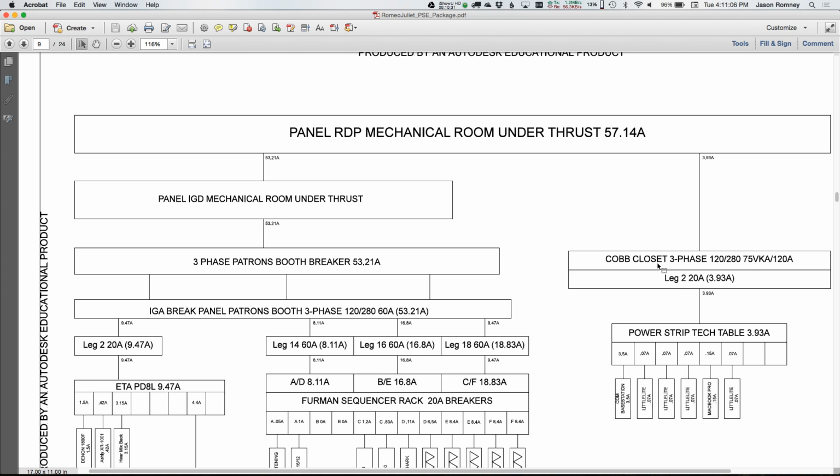If you're finding that you're pulling too much current off something, you need to find another circuit somewhere along the way. This is nowhere near as complicated for us as it is for people who do lighting and MoCo and things that draw tons more power than we do. But it still is something you have to figure out. If you figure this out ahead of time, and you know where everything is going to get connected, it can save you a lot of time in load in. And when you have problems power-wise, you'll have at least some place to start from in troubleshooting it.